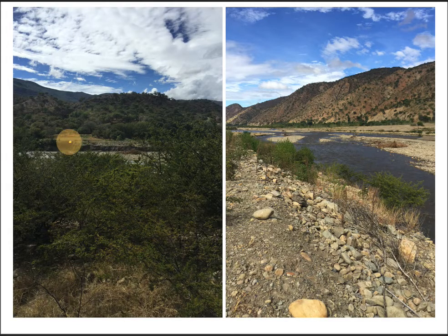You can see here, this bank is not very tall. We've got maybe 2 meters here, and then same here on this side. And so what will happen is, let's just say, okay, you have your foundation, let's say this is a tier, this is a tower, it sags down, and here at this spot even, it's pretty long bank to bank. This is a pretty wide river. Actually, what would most likely happen if you were to construct a suspended bridge here is it would hit the ground. So clearly not feasible, doesn't work there.